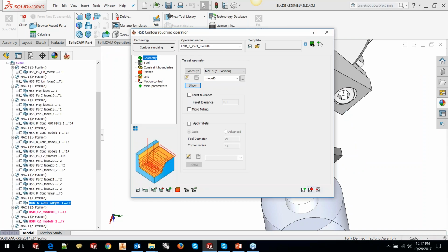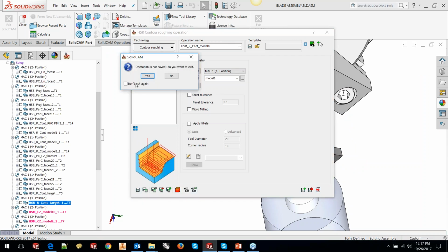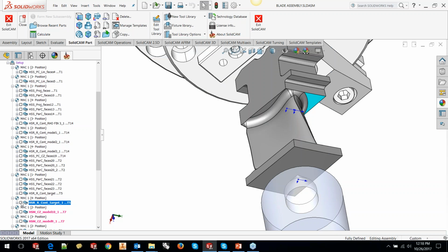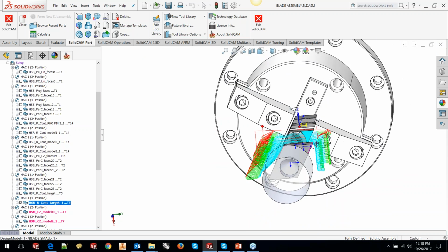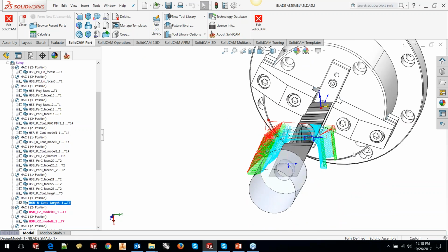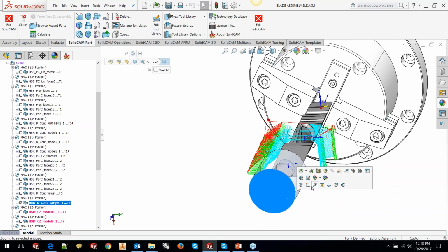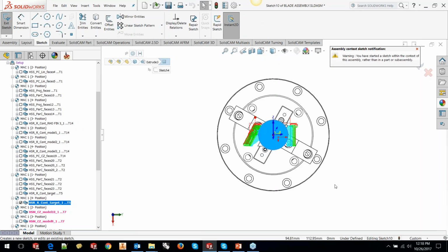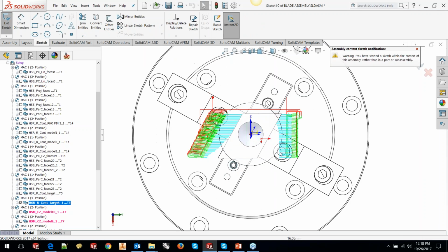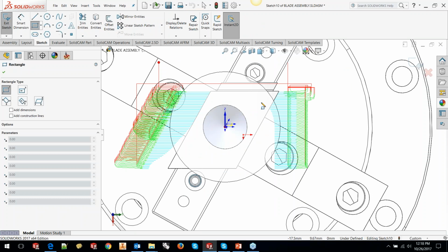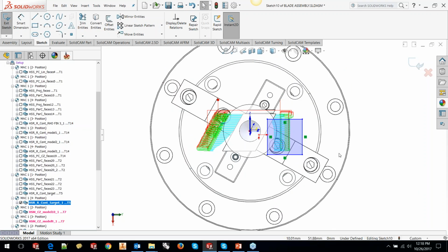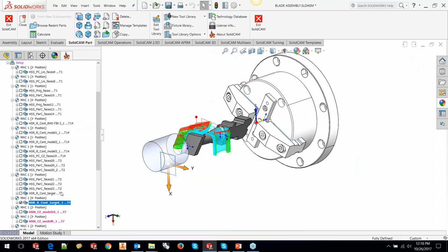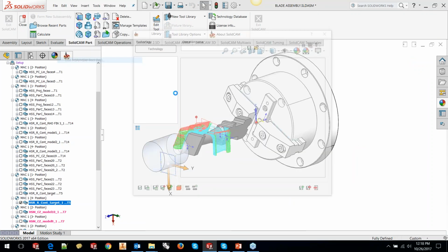Now what I did was to bring back the old toolpath, assuming that there was no surface there. So I have got the surface removed, so the toolpath is now dropping on either side. But I would like to remove some area of this. So create a sketch. Okay, and then I'd like to make only up to this point. Okay, sketch is done, can be anywhere, and we will edit the HSM and HSR toolpath.